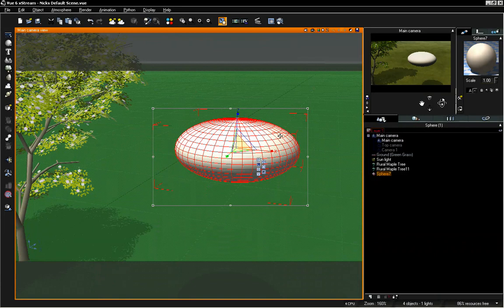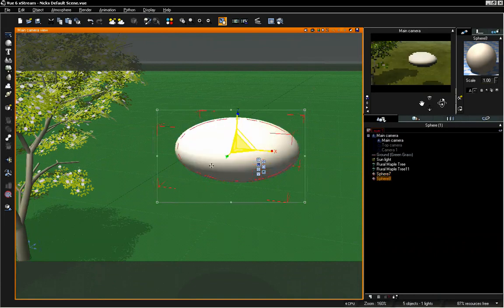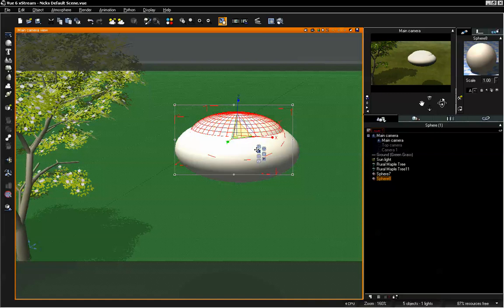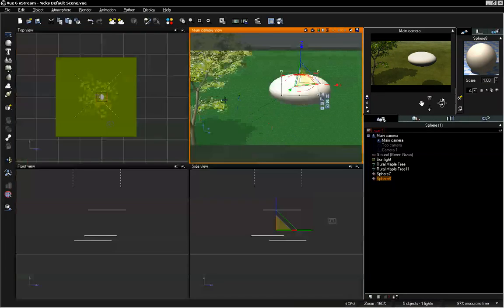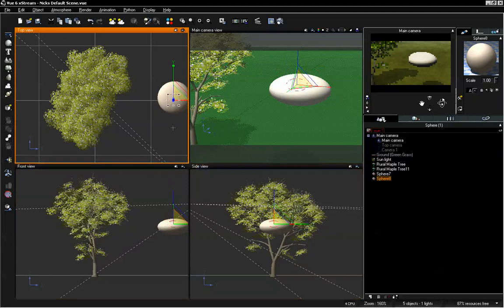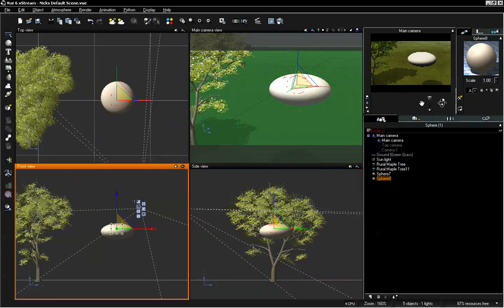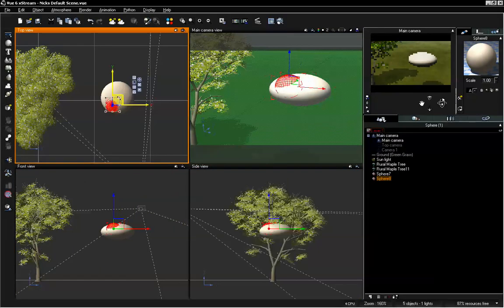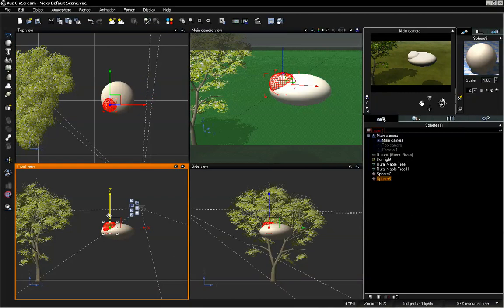And I want to create a little more variation in this, so I'm going to copy and paste the sphere and scale it down and move it up a bit. And then I can stretch that out a little more. We'll go ahead and switch to a different viewport, so we have a little more control over the scale. And I just want to place this in sort of random positions. And we can use the plus and minus keys on our number pad, or next to the backspace on the keyboard, in order to size up and down our gizmo if maybe it's a little bit too small.